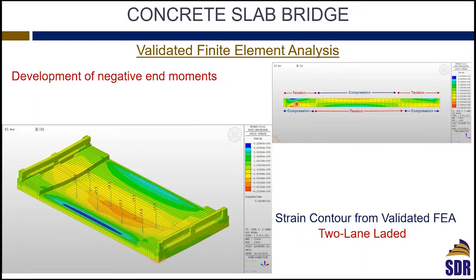And as I said, this is one of the parameters: when we design this bridge, we have to assume it is simply supported. That's the easiest way to design the bridge. However, we are in a situation where we need to look into refined analysis and load testing to see if this is fair enough for this bridge to be posted or not, so we are not underestimating the capacity of the bridge. And based on our extended experience, we have always realized that bridges can carry loads much more than what we would estimate based on code equations.